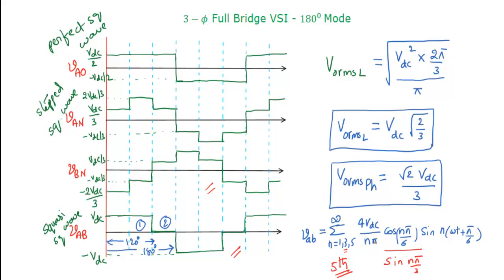Remember that. Again, the pole voltage is a proper, perfect square wave. Perfect square wave means no cosine terms, so in this case we will have all odd harmonics, because cosine is not there. We discussed this in the single phase rectifiers: n equal to 1, 3, 5, 7 and so on. That means the 3rd, 5th, 7th, 9th harmonics, everything will be there. All odd harmonics will be there. That is the difference we need to remember.